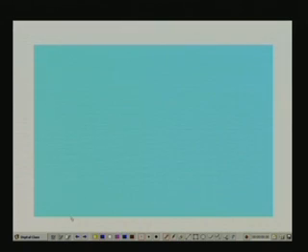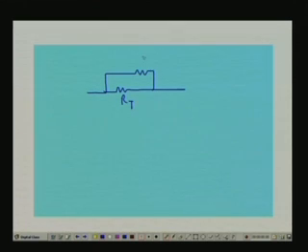Let us take a new page using a parallel resistance. So, if I take a parallel resistance, this is our thermistor RT, I am using with a parallel resistance. This is our thermistor symbol, typical. We are assuming in this case that the parallel resistance has the same resistance as the thermistor at the temperature of the T0. So, we will get the equivalent resistance, in this case R equivalent is equal to RT